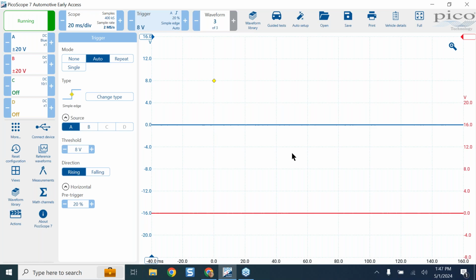You do have to have a valid trigger point to get the signal to stabilize. And remember, trigger in most cases is just for us. The scope doesn't really care, but for us users, trigger is important because it stabilizes the pattern and allows us to analyze it better, so we know where to possibly zoom in to find an issue that directs our diagnosis.